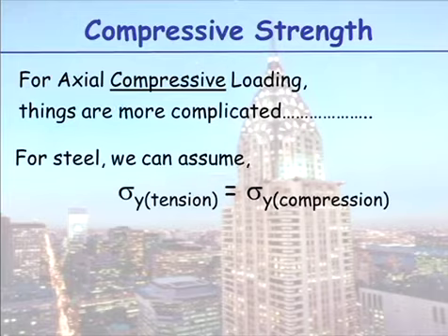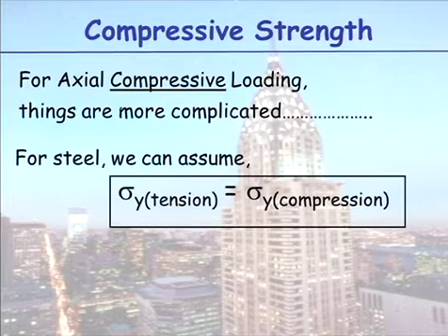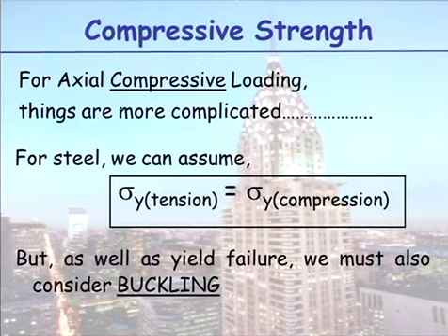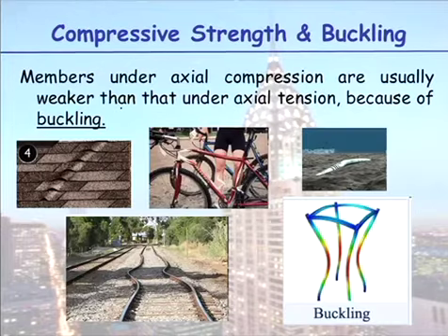So things are a bit more complicated. For steel, we can assume the yield stress in tension is the same as it is in compression. And as well as yield failure, we must also consider buckling.